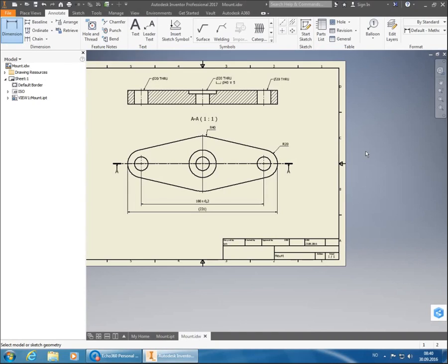But we often put in the total dimension just to make it really easy for whoever is going to create this part to go into their warehouse, for an example, and find the plate that fits and the total dimensions of what they're going to cut out of it. So that they don't have to sit down and do math in their head or use a calculator or anything, and they just get the total dimension just to see it right away.